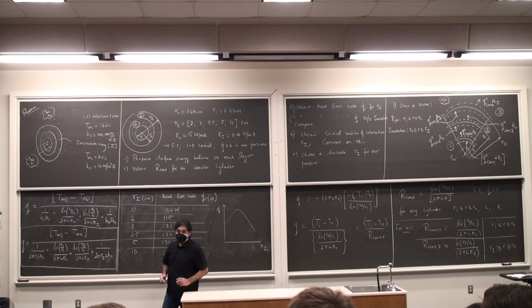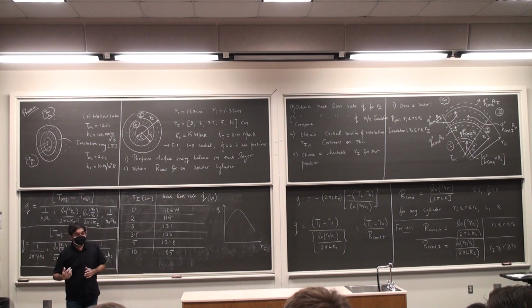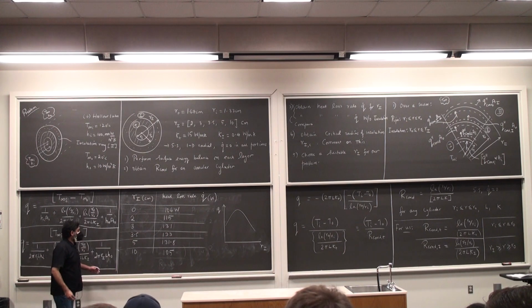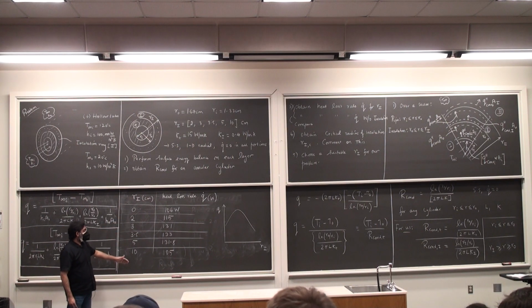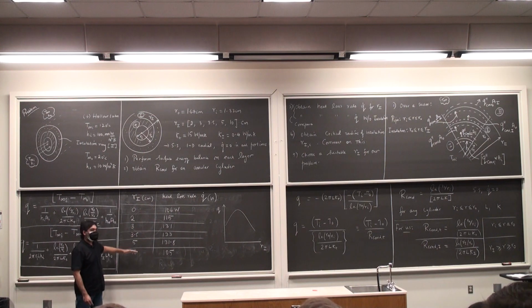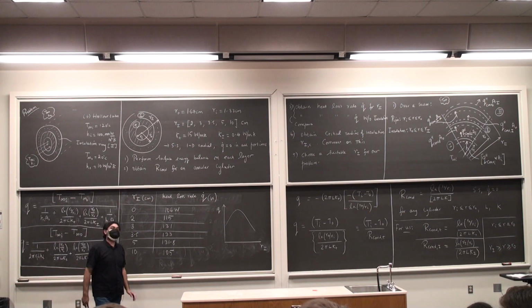That is what we are going to be calculating actually, and you will see that if my actual heat loss rate is 106 watts, and I want to just maintain it at that, I will go for a 10 centimeter insulation. It is also a function of how much money you are willing to invest and how much space is available. So those are your design considerations.